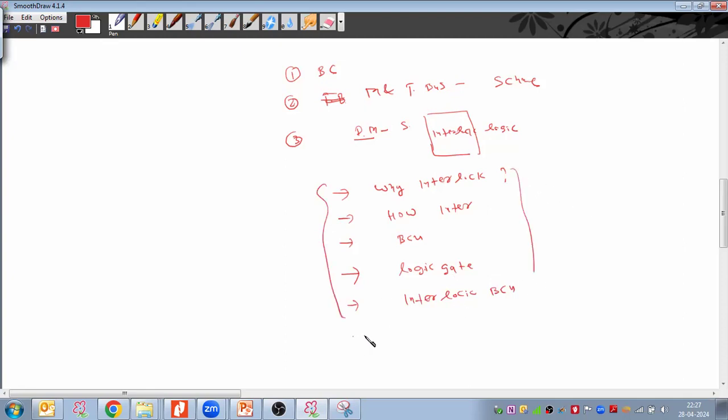Along with that, we discussed that even though we are discussing breaker maintenance and bus bar maintenance, when we prepare the layout drawing, we have to provide an approach road near the bus bar and near the breaker if the breaker voltage level is greater than or equal to 220 kilovolts.